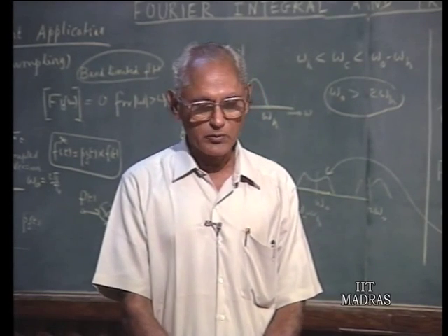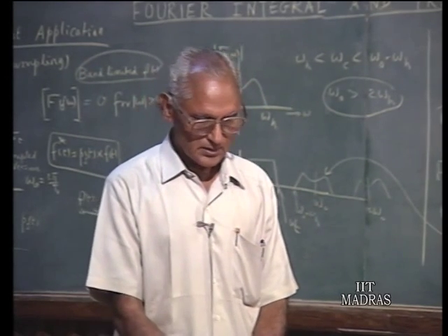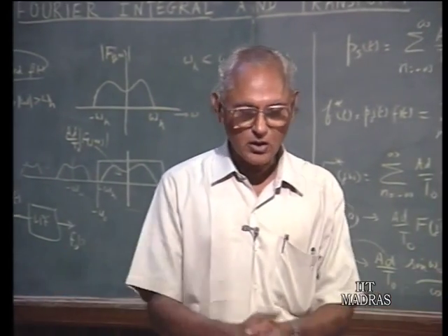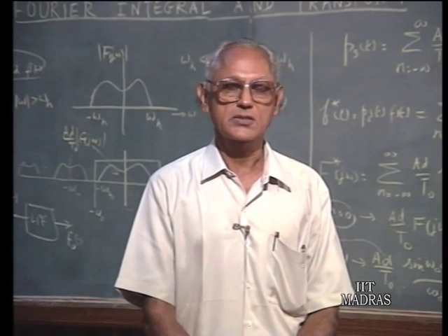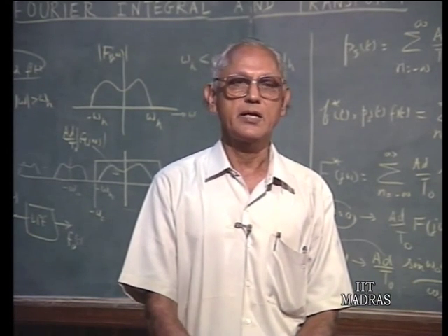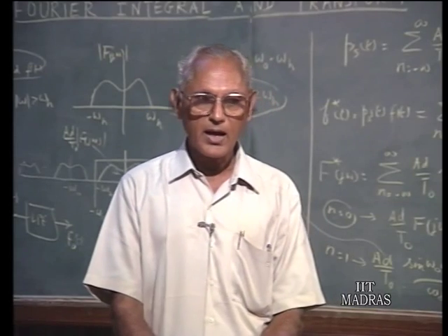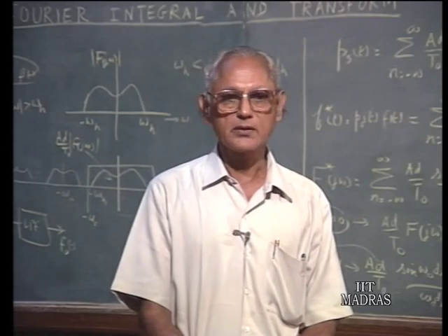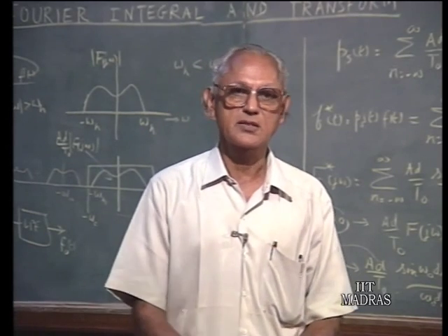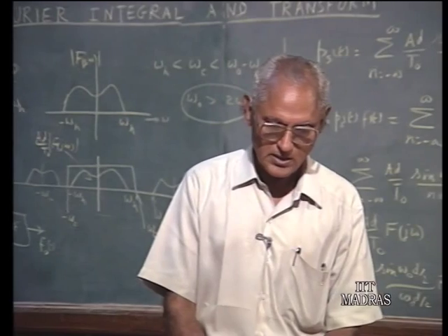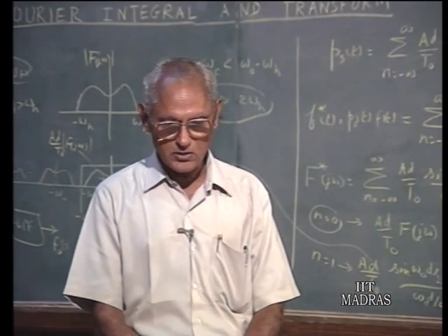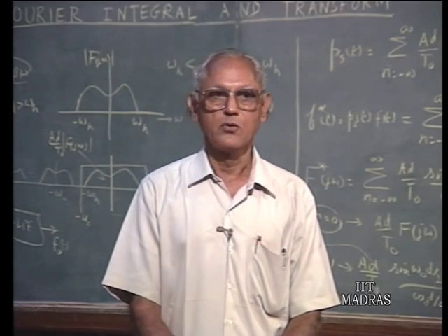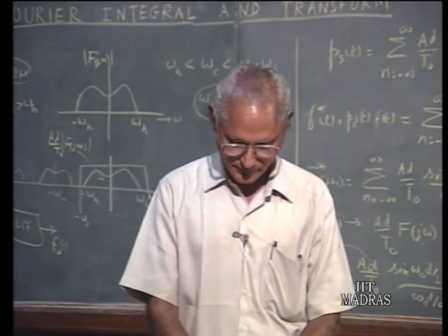Then in such cases what we can do is statistically process this information. That is, if you take a finite length of the signal, like for example a speech signal, and find out its frequency characteristics and where the energy lies in which portion of the spectrum and so on, it turns out that the statistical processing of the signal is quite a useful one. That means, even if you take other samples of the signals, the essential character of the spectrum does not change. Therefore, this way one can handle signals even though they need not be known for an infinite length of time.